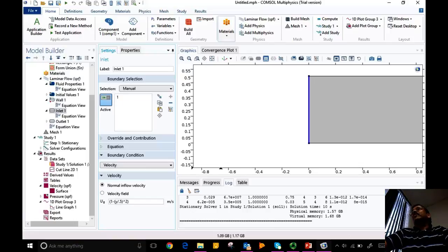The singularity will go away, right? Because as you approach this, the velocity profile will be parabolic, so it will approach zero both ways, whether you approach from the top or the bottom. But what will happen to the velocity field that you will solve? The fully developed flow will be reached earlier, but the magnitude will be whatever the flow rate is initially. So it won't be 1. What kind of initial velocity? The bottommost is going to be 1, the topmost will be 0. No, this is the wrong expression. Let's figure it out because I don't want you to go with the misleading one.